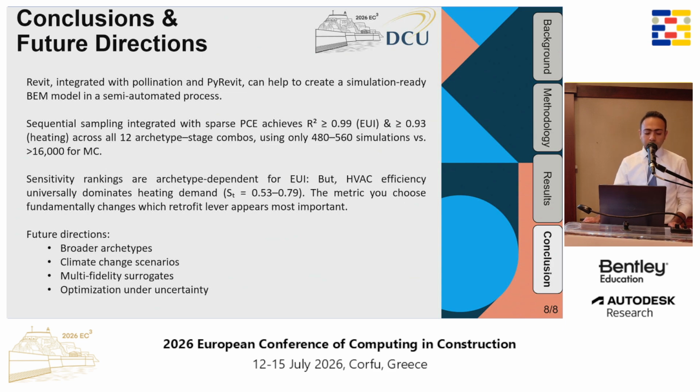So as a conclusion, Revit integrated with Pollination and PyRevit can help us to create simulation-ready BIM models. The sensitivity analysis shows that the results are archetype dependent and output dependent.